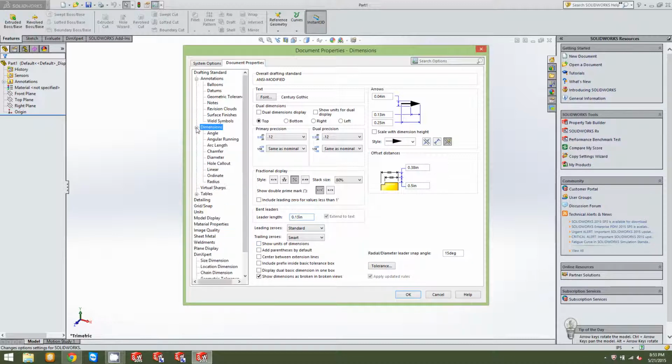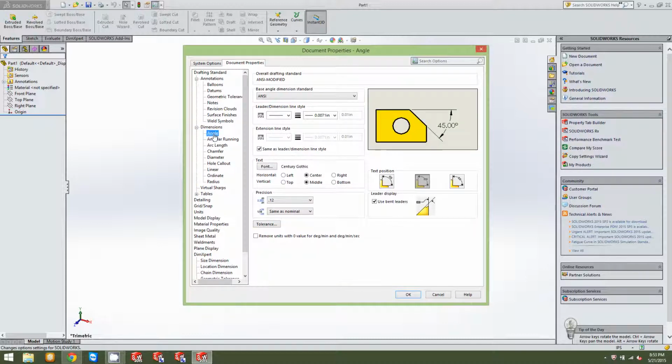And then you got that little plus arrow, and you can open it up again. We will want to click through on each of these. You can pick your different styles of where you have your degrees set, what the angles are at. I prefer horizontal break degrees for the angles. Using bent leaders, there's where you set the font, set where it breaks it at. Precision 2 decimal points.